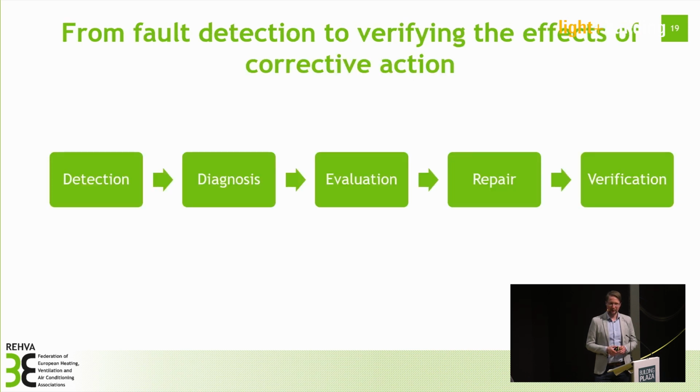In a similar way as on the MLOps side, I would say that on the FDD side, the research concentrates only on the first steps of the process in the practical world. Here in FDD, it's quite much about detecting the anomalies in the data. But after that, you need to diagnose the cause of the anomaly. It could be quite easy to find the reason, just checking the building automation system, or it might need some expert to go on site and do a more detailed reasoning of the problem.